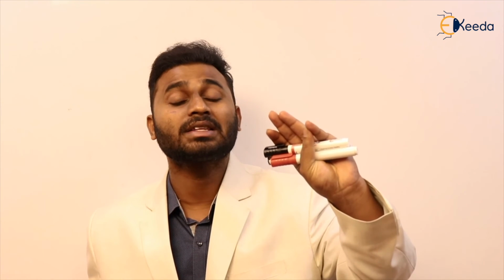Usually we manufacture a beam or I section as a plastic section if we follow B by TF as 9.4. If we follow B by TF as 10.5 and manufacture, then it is a compact section. If we follow D by TW as 84 epsilon, then it is a plastic section. So if we follow those ratios, the sections will be plastic, compact and semi-compact. But usually a slender section is a plate girder, which is a built-up section. That we are going to discuss in plate girders. Design of plate girders I'm going to explain.